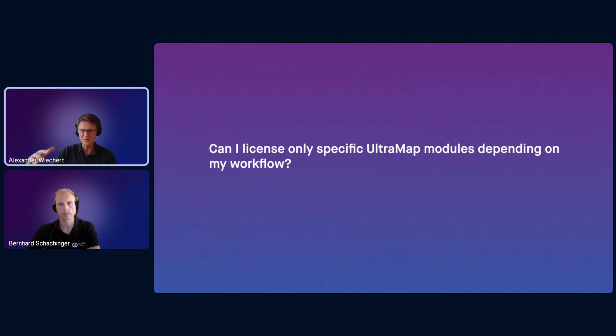So when you want to use the dense matcher, you need to have essentials and AT and the dense matcher. You cannot use just the dense matcher because the dense matcher is using the data from the previous modules. So you can put your workflow together, and we have interfaces to export and import data. But this is a kind of a waterfall model where each module sits on top of the other. So when you want to have the last module, the 3D one, you need the full stack. When you want to have AT, you need essentials and AT and so on.